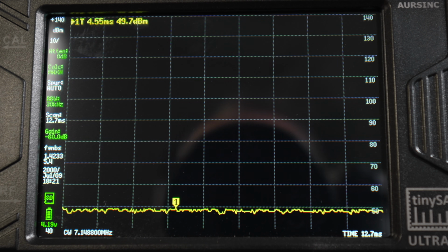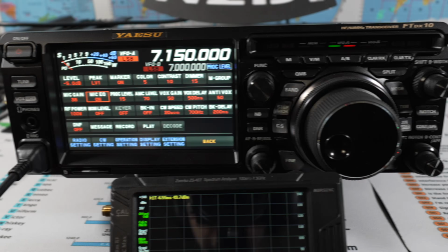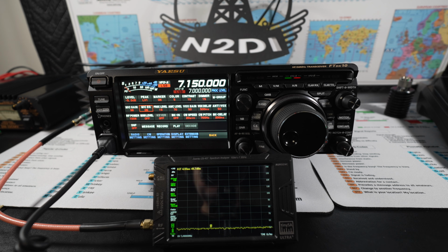If your radio is set to 100 watts, you're going to peak at 100 watts. So to sum that up, when you're using single sideband, your peak power will be whatever you have set your radio to. If you set it to 100 watts, you're going to be very close to 100 watts, if not exactly 100 watts. But your power meter is going to show you your average power. The only thing that really impacts your average power is your microphone gain and your processor level. What all these settings really do is help your intelligibility, and that helps a lot in poor conditions when your signal is weak or when you're dealing with crowded bands. So it's not always about power output. You want the person on the other end to be able to understand what you're saying in those challenging conditions.